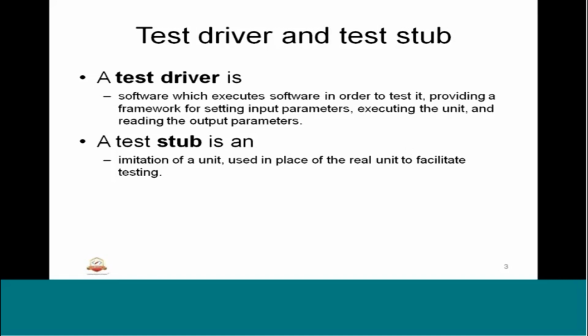So okay, a test driver. It is software which executes software in order to test it. That means a test driver is again a piece of software. It's test software which executes the embedded software unit which is under test, to test it. So it provides a framework for setting input parameters, executing the unit and reading the output parameters. I have a diagram in the next slide. I will explain, and you can understand better.